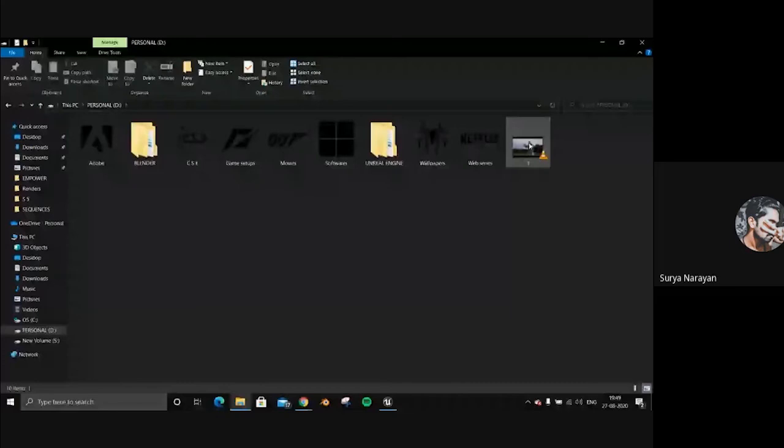Oh, okay, I can't do that. I'm gonna put it somewhere here. Capture. Save selected, and you can actually preview the rendering here. The rendering is really fast in Unreal Engine because it's real-time rendering. So yes, we have now rendered out a movie or a sequence. Let's see where it's located. There we go. There we have our video right there. So yeah, that's how you basically render out a video or a sequence that you have created in Unreal Engine.